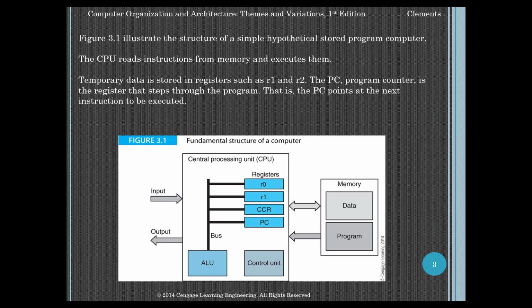So a computer with 32 general purpose registers might require only 5 bits in the instruction to specify a register, whereas it takes 32 bits to uniquely access one of these 4 gigabyte locations in the main memory, right? You can see the difference. And so this is why we have different addressing names for registers versus our main memory.